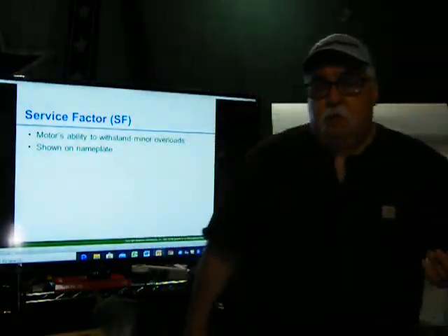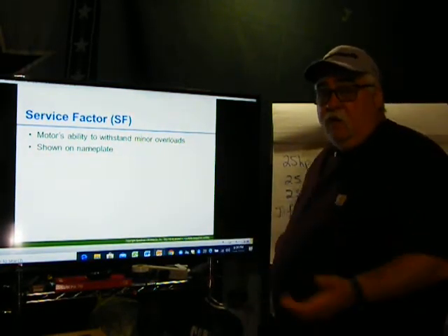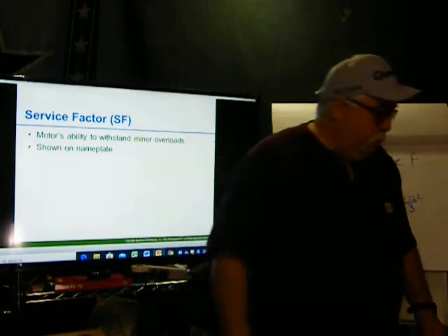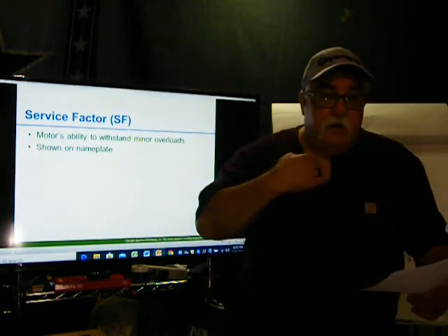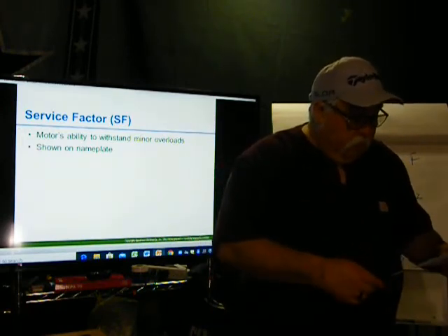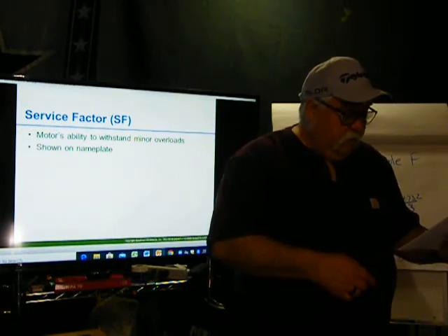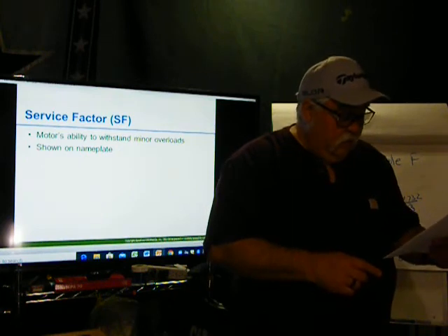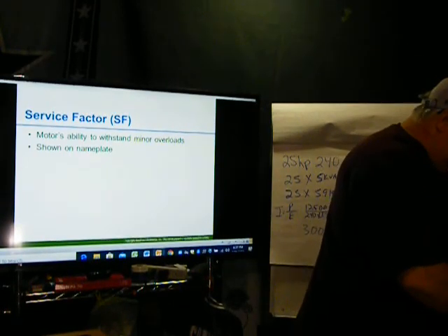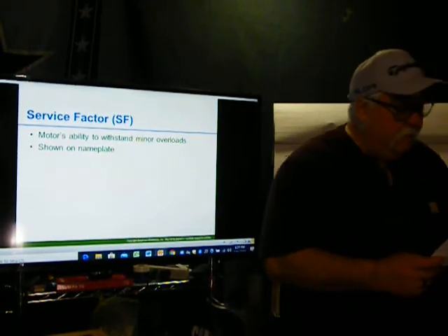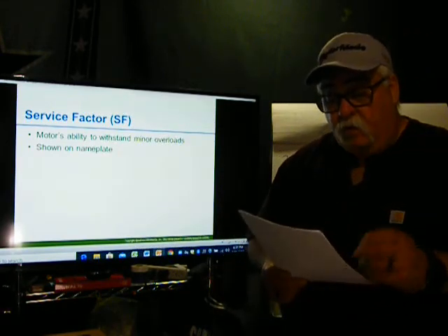So we put in these thermal protectors. Thermal protectors are called overloads, and out in the field, heaters. The little heaters that we put on the starters, which I talked about in Electrician 2, in the residential part, when talking about motors. So again, this is article 430.32 on page 304. A separate overload device that is responsive to the motor current. This device shall be selected to trip and shall be rated no more than the following percentage of the motor nameplate full load current rating.